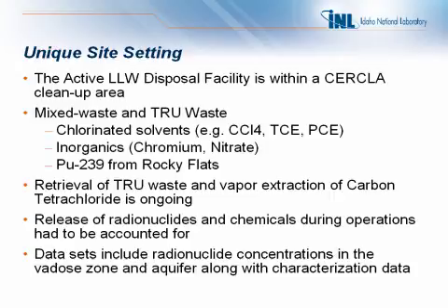So in doing the performance assessment and also the RAFS, we had to account for the fact that waste was being continuously disposed at the time, because there were releases occurring before the end of the simulation. Typically, you might start with some initial condition. We dispose some 500 curies or whatever of a radionuclide and then start a simulation. Our simulation had to progress while we're disposing, increasing our inventory, and releasing at the same time. So there was quite a bit in the way of source term modeling.